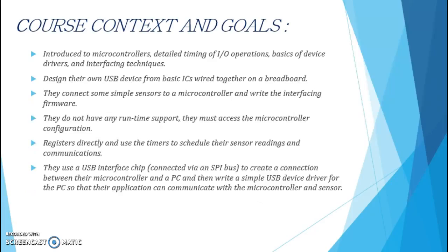Next slide. Course content and goals. Intuitive microcontroller, detailed timing of input-output operation, basics of device drivers and interface techniques. Students design their own USB device from basic ICs wired together on a breadboard. They connect some simple sensors to a microcontroller and write the interfacing firmware. They do not have any runtime support. They must access the microcontroller configuration registers directly and use the timers to schedule their sensor readings and communications.